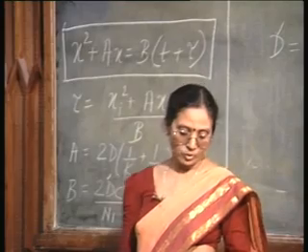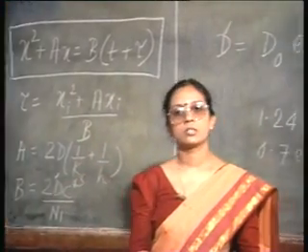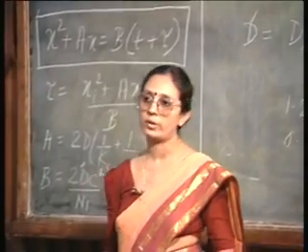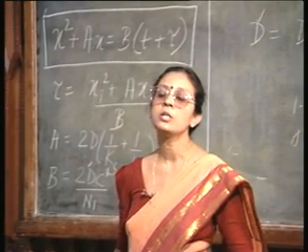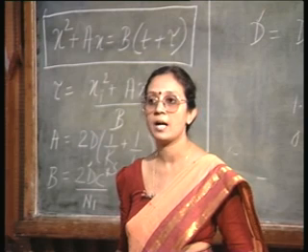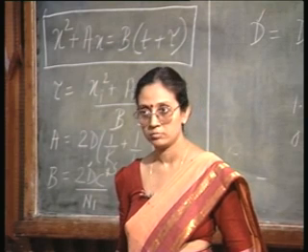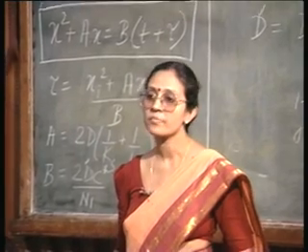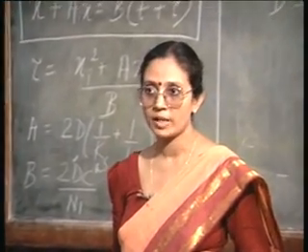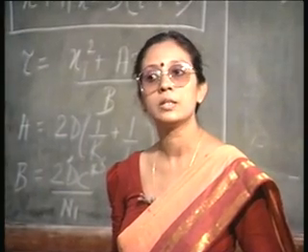So, now therefore, we have seen that the oxidation growth rates are higher for wet oxidation than for dry oxidation, and also the growth rates will be higher at higher temperature, right. That is, if you carry out the oxidation at higher temperature for a given amount of time, you would expect to grow thicker oxide.